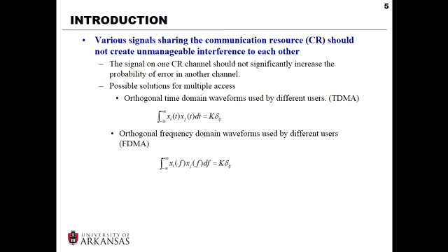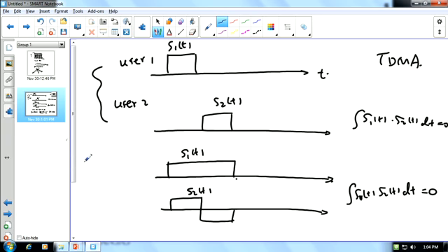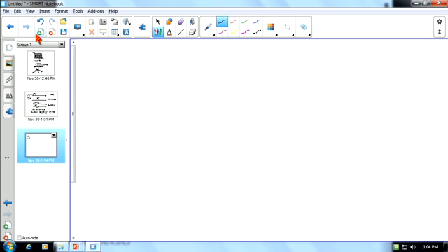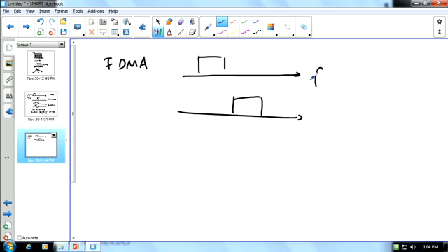So that's the conventional FDMA system. Okay. So for conventional FDMA, that's frequency, and we have different frequencies for the different users. And actually for OFDMA, we no longer use this kind of non-overlapping allocation. We use an overlapped waveform in the frequency domain. As long as they are orthogonal, then we are fine, okay? And for OFDMA, the channels do have overlapping, but they are orthogonal,